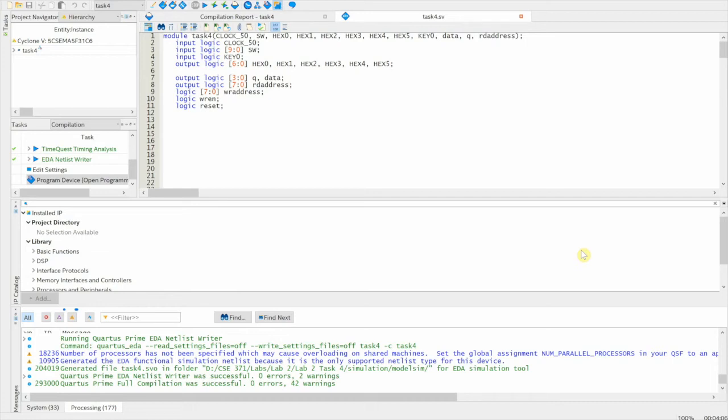The purpose of this video will be to demonstrate how to use the SignalTap Logic 2 Analyzer tool in Quartus Prime. Before I begin, I just want to stress how important it is to test everything in ModelSim and generate your waveforms before you actually plan on downloading it to your FPGA. This should be habitual by now, but it's a very important step.